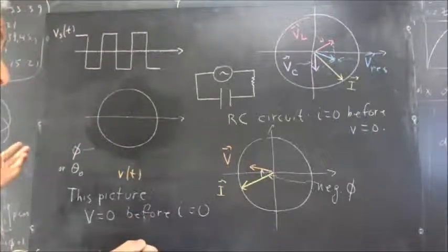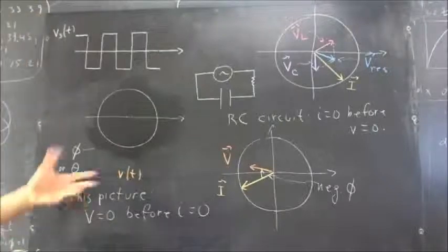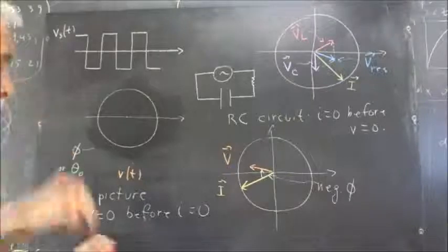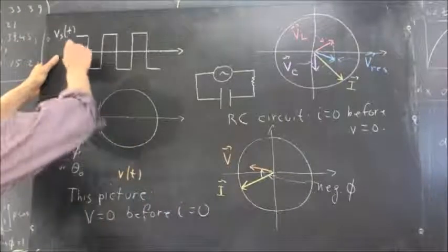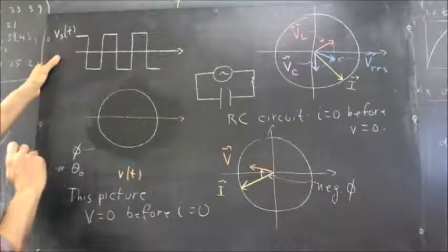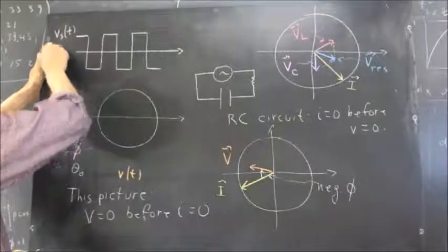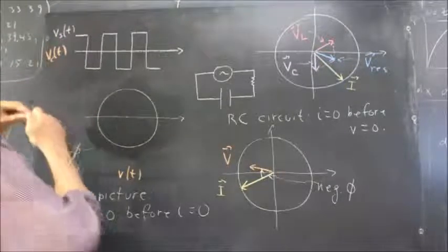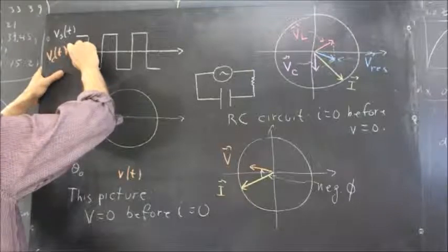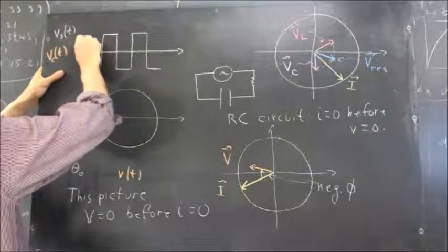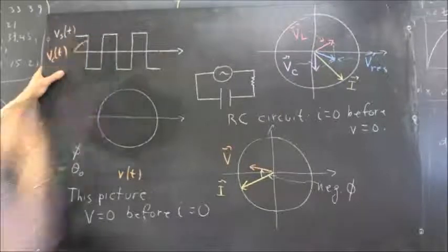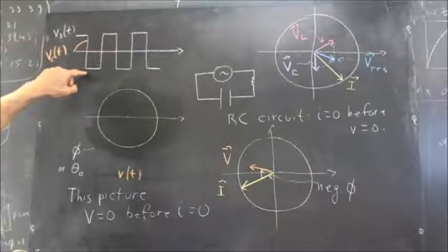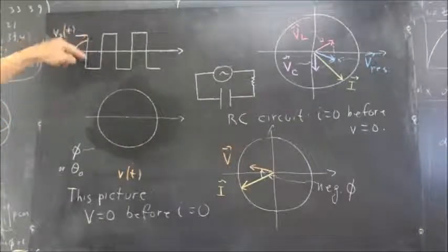Okay, well, what happens if we have a capacitor in the circuit and we have some resistance? The battery has resistance, if nothing else. Well, if we start, let's say here, with a capacitor uncharged, the capacitor voltage, which we'll designate by V sub C of t, starts at 0 and begins to approach exponentially this voltage here. And it continues happily doing so, but pretty soon it gets cut off. So now it's got to exponentially approach this voltage.